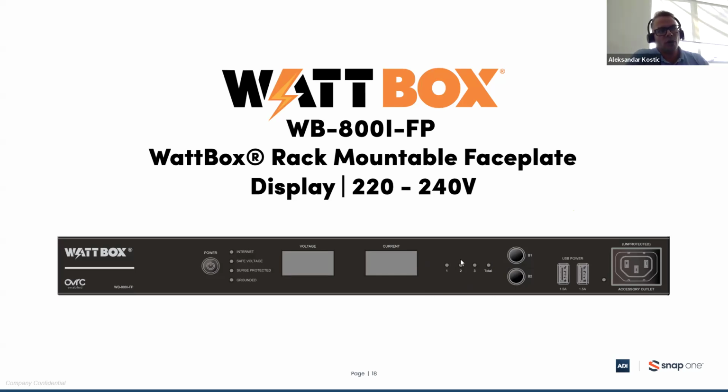And also, if you have multiple WattBox units connected, like all 3 connected, if you press and hold B1 and B2 buttons together and keep them pressed for 5 seconds, in that case, it will restart all connected WattBox units. So the faceplate provides a certain level of control of the WattBoxes connected on the rear side of the rack as well.